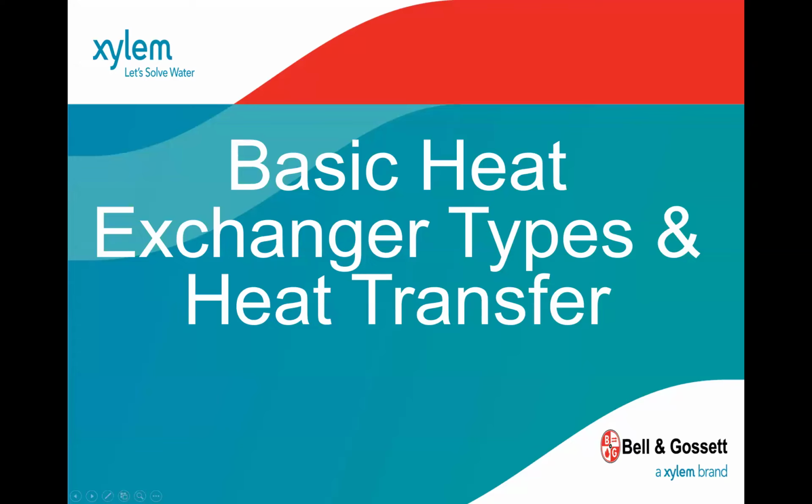So for the shell and tube heat exchangers, the big advantage that you'll see a lot of people selecting is that you have a lot of options for materials. So if you want 316, 304, whatever material type you want, temperatures, pressures, it's a very wide range. They're pretty easy to custom manufacture, unlike maybe a plate and frame where you're not going to be making so many custom patterns. Even though you'll get custom mixes, you'll have blends of different plate patterns, but most likely you see a lot of that.